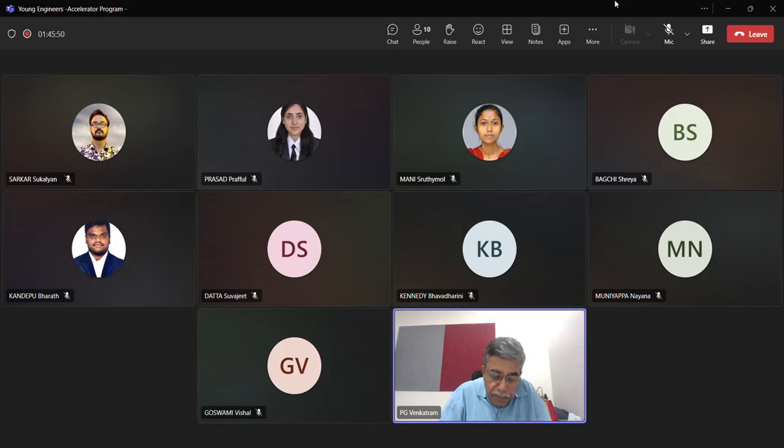Some rule of thumb that used to apply in the early days: for short span, live load is the bigger component in the total load than dead load. In short span up to 30 meters, it would be roughly 60% live load, 40% dead load. Beyond 30 meters, 30 to 40, it might be 50-50. 40 to 60, 70, it will be something like 60% dead load and 40% live load. And 100 and above, it will be almost 80% dead load and 20% live load.